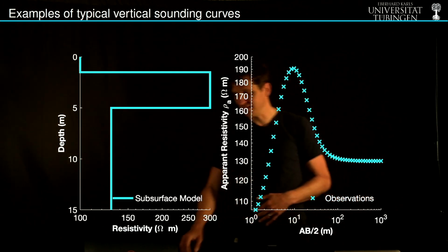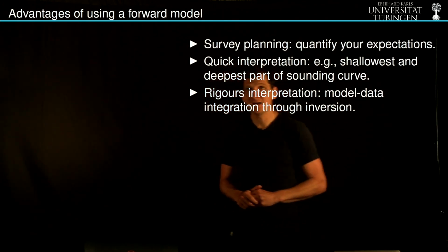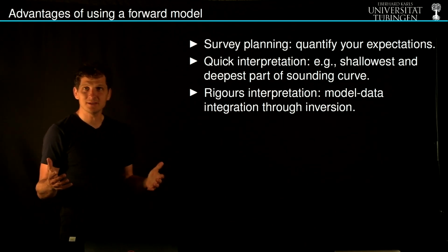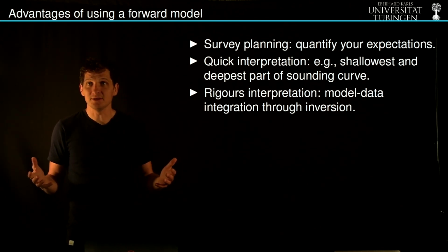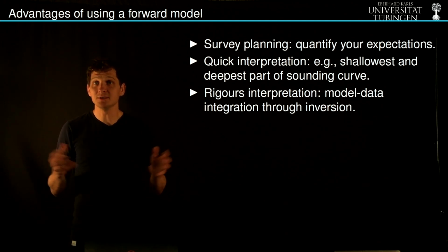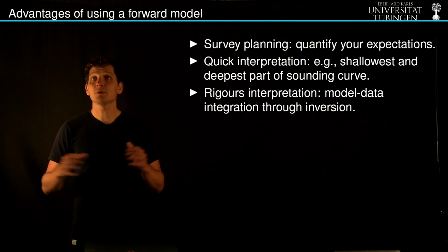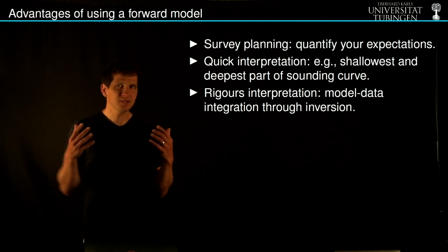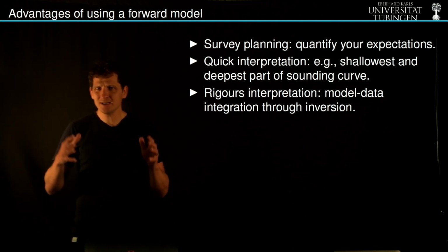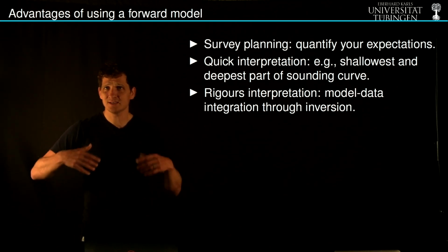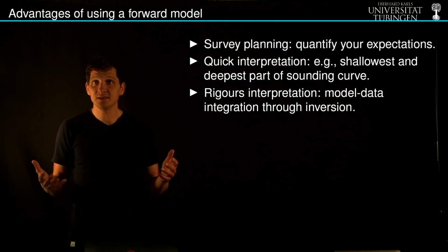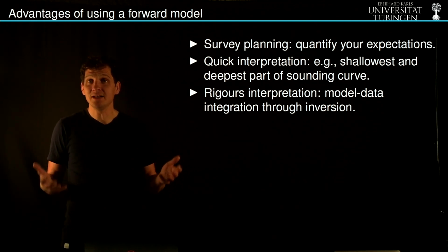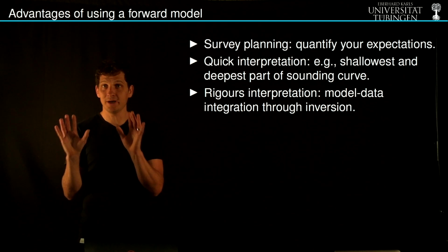How can you account for that? Well, first, before we account for that, we kind of celebrate now the usefulness of such a forward model, and you will do this in the exercises. Yeah? Such a forward model is hugely beneficial to plan your survey. Okay? So you can go to the literature, you analyze, okay, what is the geo and environmental context that I'm in, which resistivities do I possibly expect, what are the depths that I'm really interested in, okay? So all of this you know ahead of time.